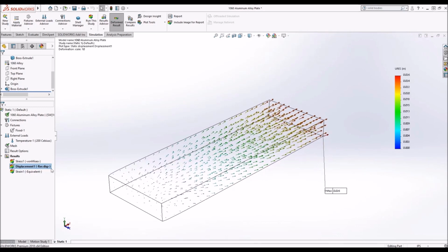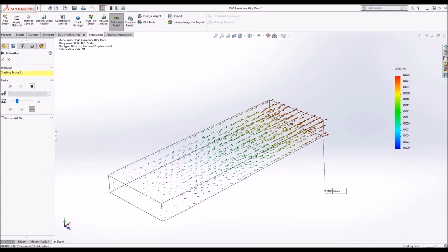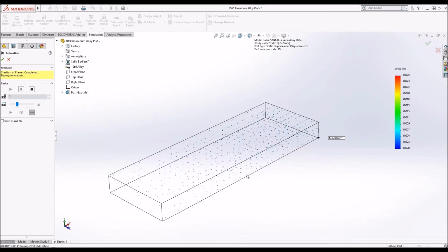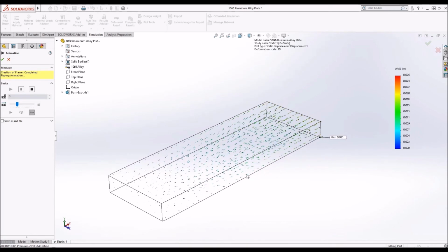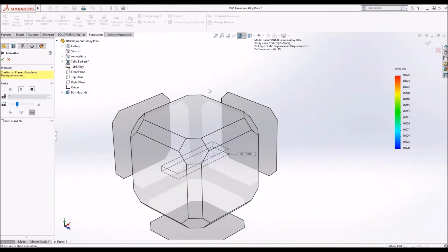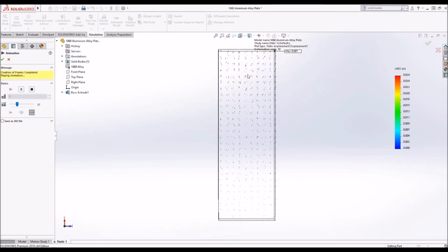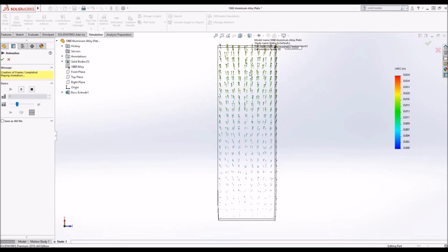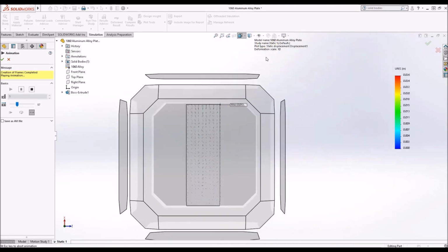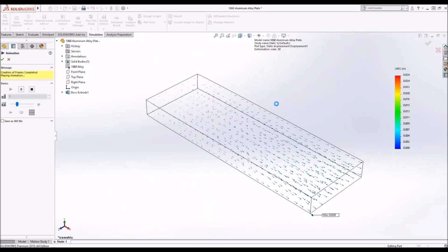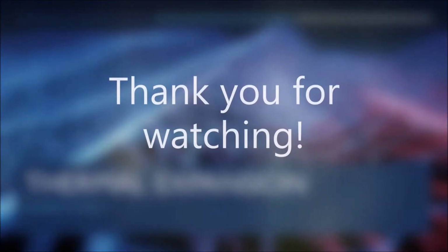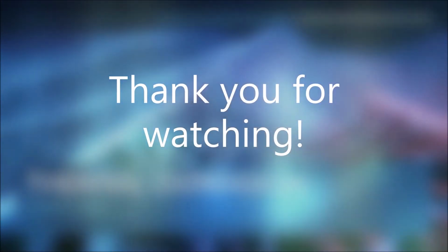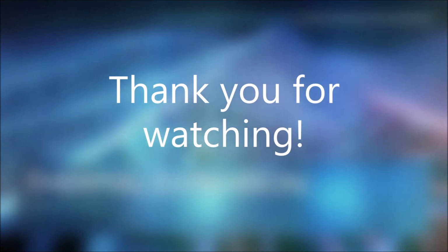In conclusion, we have calculated the expansion of a given part by simply using the material CLTE and by defining the temperature change. We have also shown that SolidWorks simulation is a great tool to analyze such problems in greater detail. These types of engineering tools allow you to make sound engineering decisions quickly and efficiently and decide on whether the material is safe to use under known conditions. So make sure you take advantage of their potential.